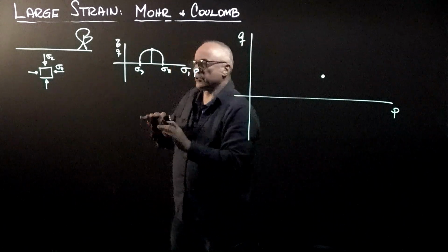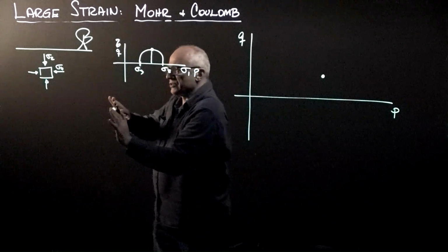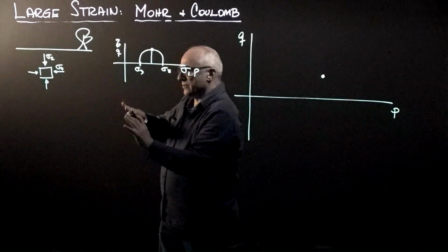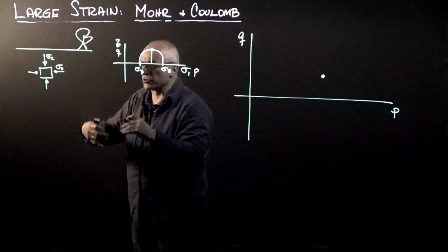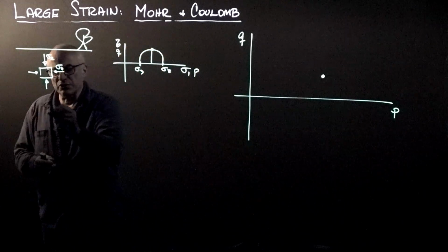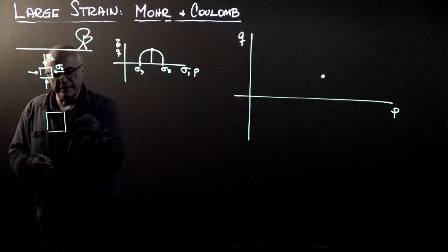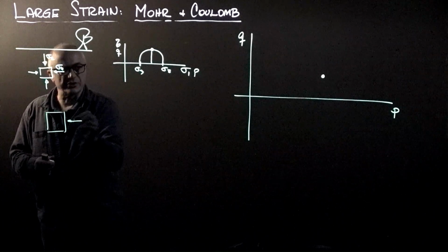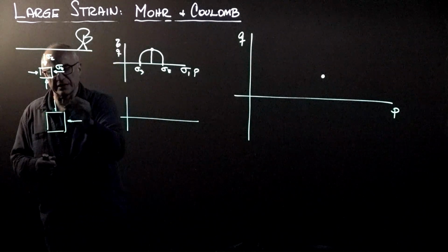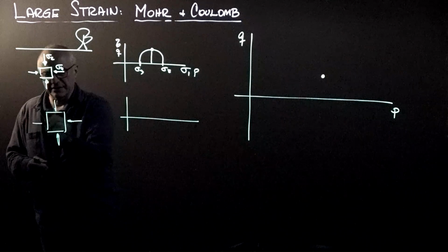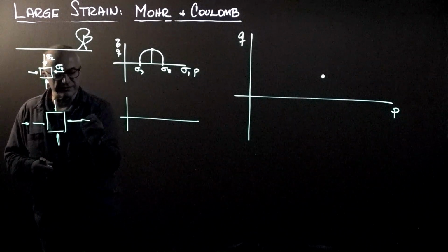Now we could have a situation where we begin pushing horizontally because there is a bulldozer plowing into it, or there is tectonic motion. If we push horizontally, then the horizontal stress begins to increase. Look what happens to the Mohr circle. Of course, you still have the vertical, but the horizontal stress increases faster.